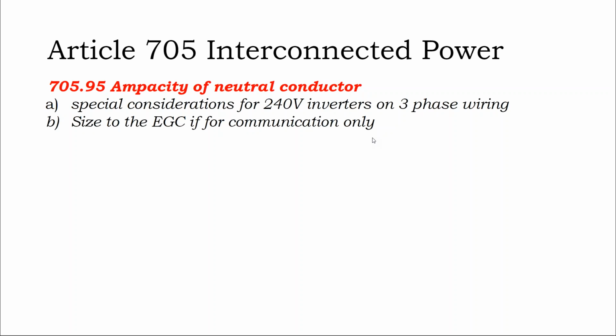Ampacity of the neutral conductor. There are special considerations for 240 volt inverters on three-phase wiring versus 120/240 with regard to oversizing.